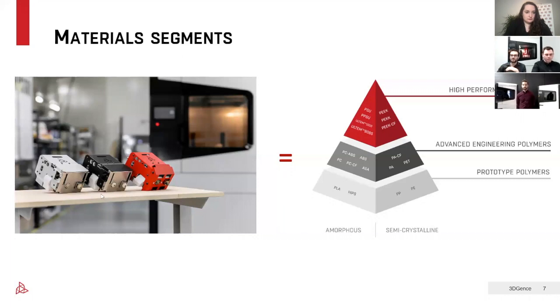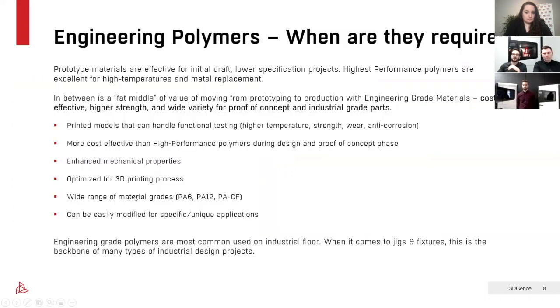Okay, and since the topic for today is engineering plastics, we are focusing on the middle layer of the material pyramid: the materials that are specifically chosen for a distinguishing feature and that are also cost effective in their applications. Such materials like polycarbonate or polyamide, and ABS for that matter, as Mateusz has mentioned, have a very specific feature that might make them very applicable in specific regions of industry.